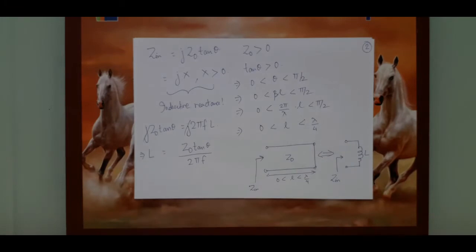And that is amazing. Because for many applications, you may not get the value of inductor that you want. So in that case, you have to resort to either using series combination, parallel combination, or if it so happens that the value of L that you want is very high or very low, in that case, using transmission line to realize an inductor is a very, very interesting approach.